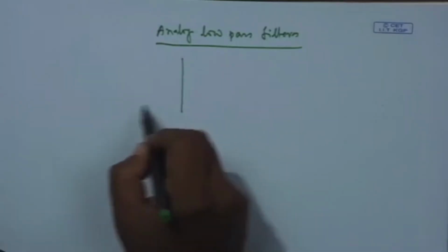Now we have discussed analog signals and systems briefly, but all essential features were discussed. Now we will be considering one rational model, that is, we will design an analog filter which will be causal and stable, and rational, that is, the transfer function will be a numerator polynomial divided by a denominator polynomial in S, because we know that this can be realized using differential equations. Those in turn can be realized using op amps, differentiators, integrators. So, using them.